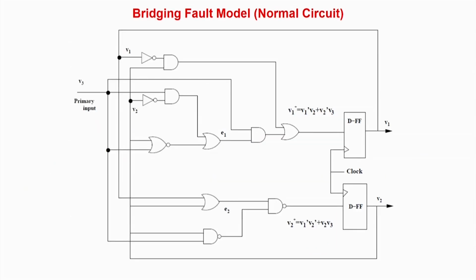So let us take a very simple circuit example which we will be using throughout. Now I will be mainly talking about sequential circuits as examples, because we already know the scan chain. Scan chain means you can directly set or reset your flops. So these are simple circuits, with 2 lines. Any 2 lines may have a bridging fault. So now one thing is there.